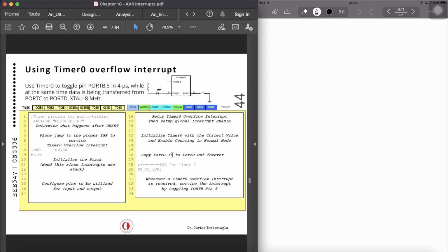So let's analyze it. We need to use timer interrupt, timer 0. Okay, and we have to be careful over here. How are we going to configure the TCCR0 as we are using timer 0? Let's use the normal mode. It says timer overflow interrupt. So we have to use the T0 interrupt enable. We have to enable that one. And also no prescaling, normal mode. So these are all 0, 0, 0. This will be 0, 0, 1. Okay, that's the only difference over there.